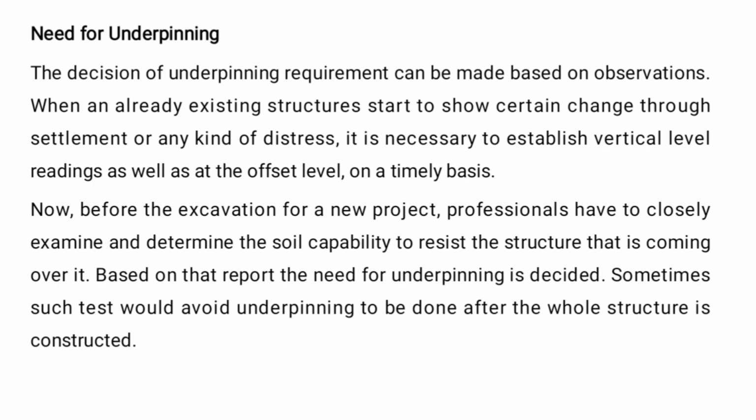Need for underpinning. The decision of underpinning requirement can be made based on observation. When an already existing structure starts to show certain change through settlement or any kind of distress, it is necessary to establish vertical level readings as well as offset level readings on a timely basis.